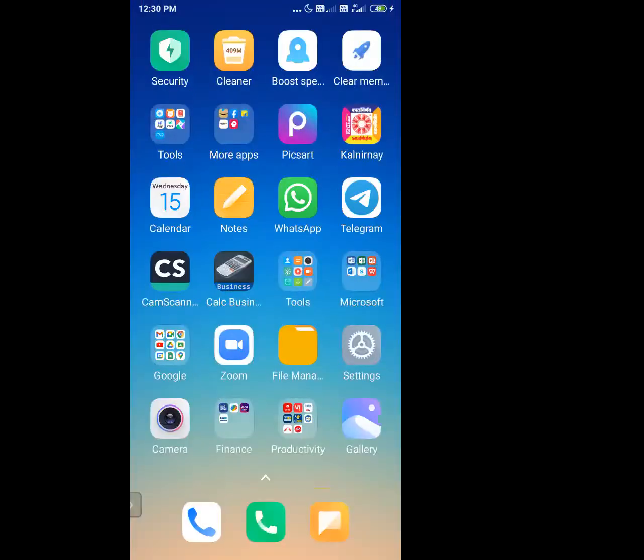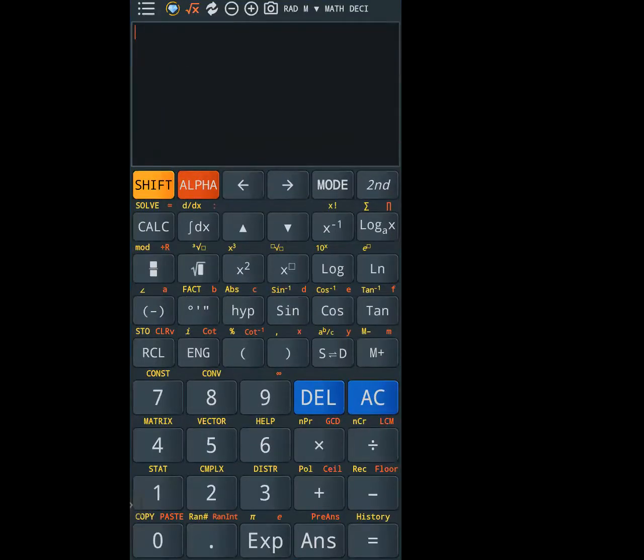Okay, let's do this calculation. So what will we get? T2 = 290 into (1000 by 100) raised to power (1.425 minus 1) upon 1.425. Okay, you can check what temperature we are getting.